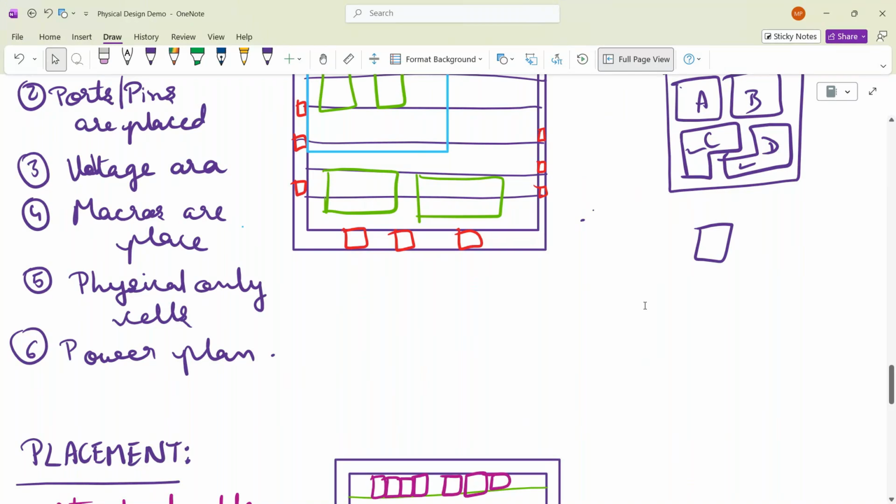Can we learn stage by stage analysis, like how to fix congestion at synthesis, floor plan, and these stages, and fixing timing? We are doing that. So you are focusing on more analysis, right? We are doing the flow and doing analysis in between. Yes, we are doing. At each and every stage, we are doing congestion analysis and timing analysis, and we are giving fixes also.